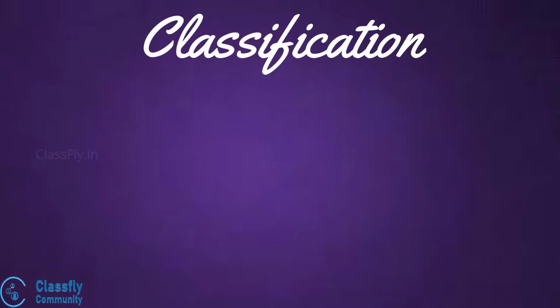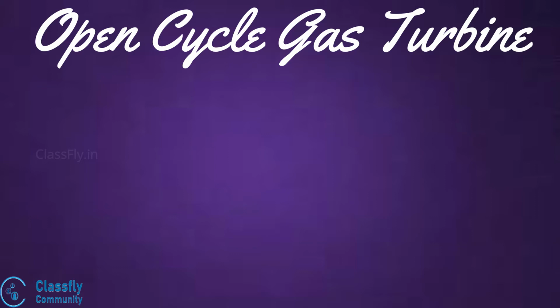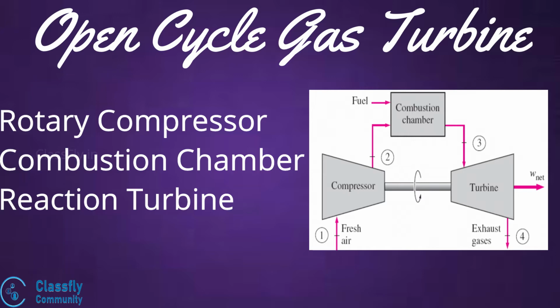Next, moving on to the classification of gas turbines. Well, they are classified into open cycle gas turbines and closed cycle gas turbines. Let us study the open cycle gas turbine. Well, this consists of a rotary compressor, a combustion chamber, and a reaction type turbine. Here it is important to know that a part of the power which is developed by the turbine is required to drive the compressor.